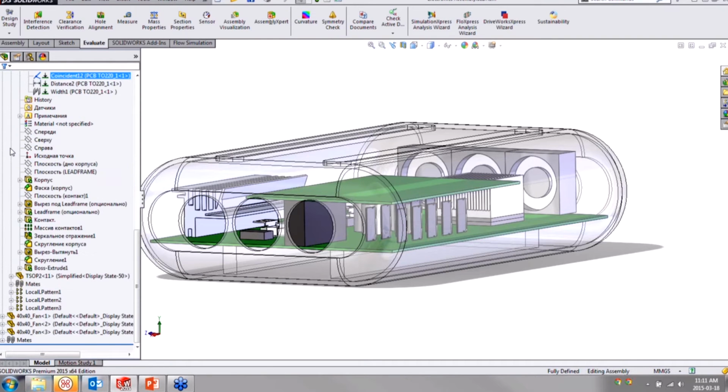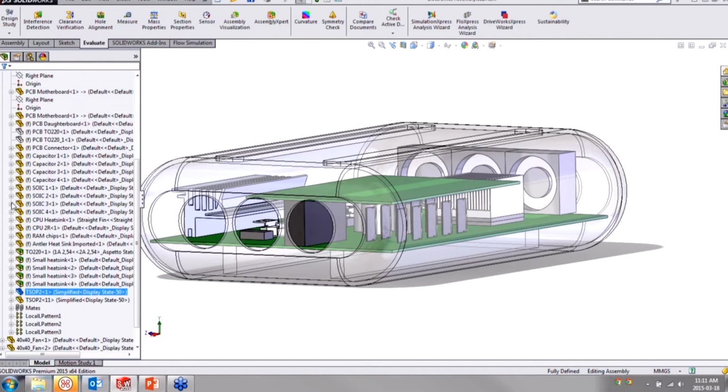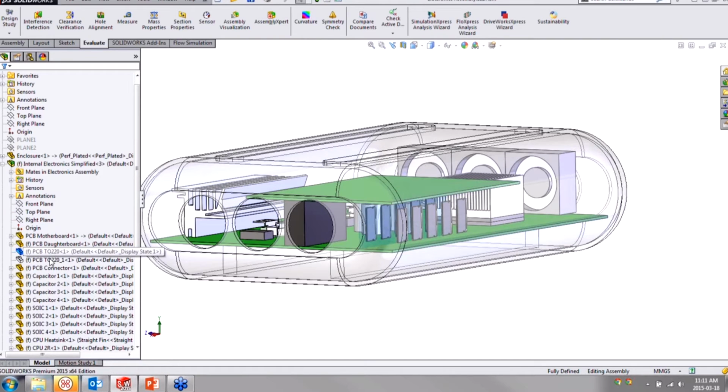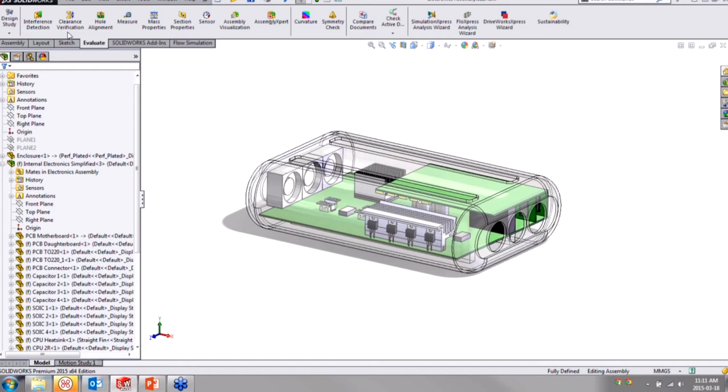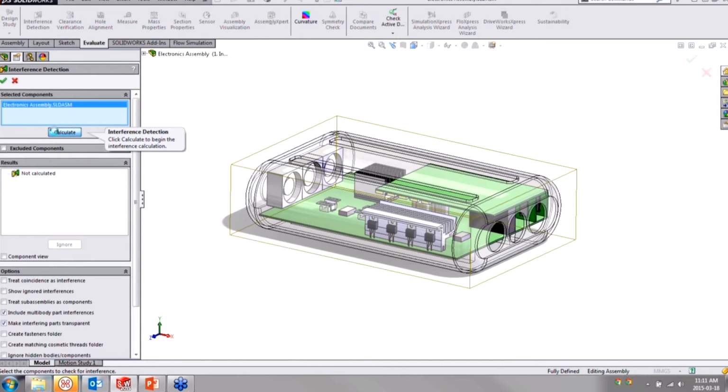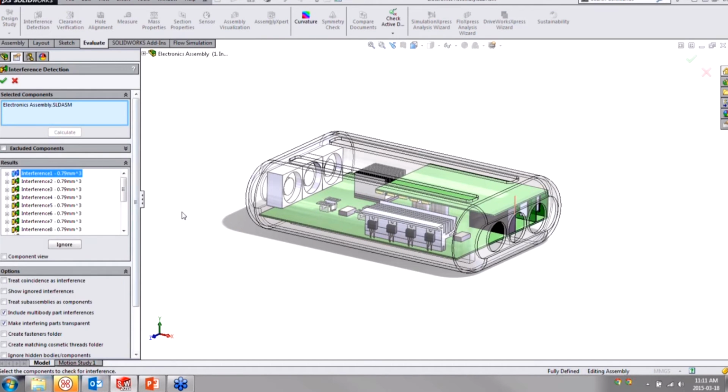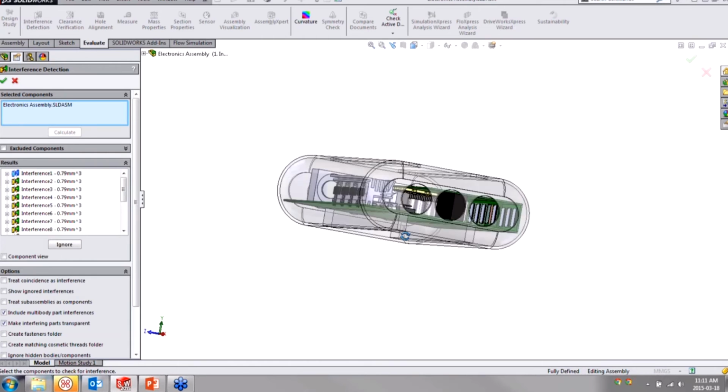just want to poke through, decide whether it's a problem, and make any changes that are necessary. Okay. So that should help clean things up. I can bring those two parts back now. And let's just double check that I fixed that properly. I'll run interference detection again. And oh, looks like I didn't actually fix it properly.